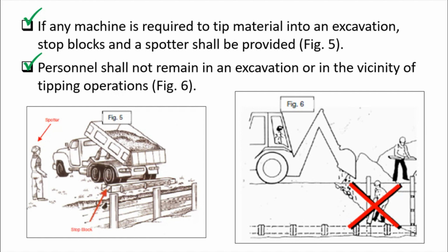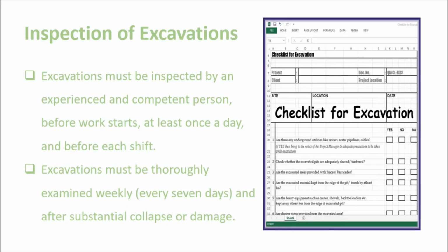Remove them before you tip any material into the excavation, and once it's completed, you can advise them to return and continue their job. So always make 100% sure that no people are inside the excavation before tipping any materials.